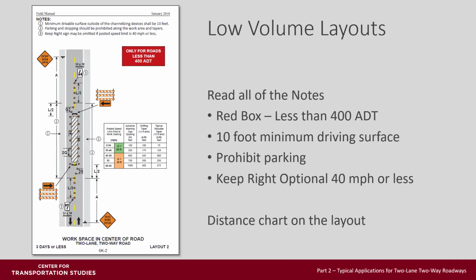In layout 2, again, remember to read all the notes, especially the red boxes, and I'll quit reminding everyone of that as we move forward. This layout has a sign and device spacing chart on the layout. Note that the drivable surface is a minimum of 10 feet wide unless approved by the local agency. Parking should not be permitted along this area.